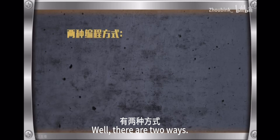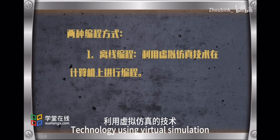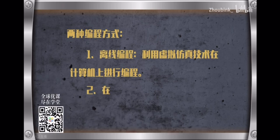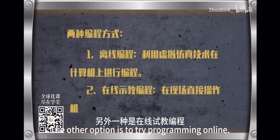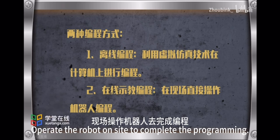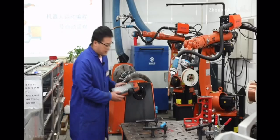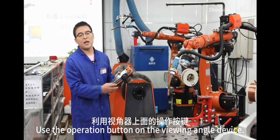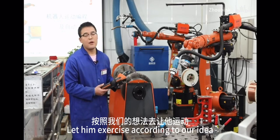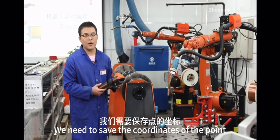What about the programming? Well, there are two ways. One is offline programming, using virtual simulation technology to operate the robot on the computer. The other is online teaching programming, using a robot teach pendant to operate the robot on site to complete the programming. What we're using today is online teaching programming. We use the operation buttons on the teach pendant to operate the robot and let it move according to our idea. During movement, we need to save the coordinates of the points.